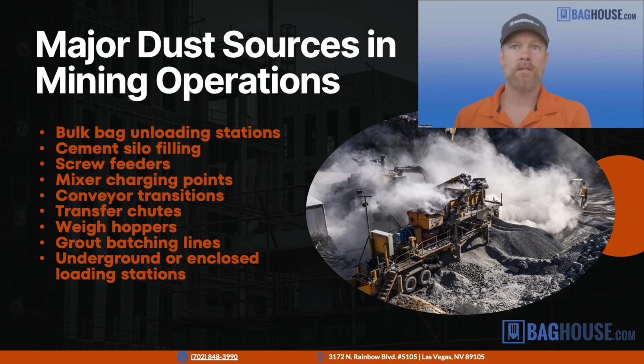If you're pulling dust collection air out of a facility, we also have to consider the balancing of the facility. So we don't want to have the doors slamming shut because we're pulling 60,000 CFM out of the facility and we're not recirculating it or making up that air. You can also be pulling dust in from outside. So usually we would look at recirculating air through the dust collector back into the building or have some sort of a makeup air unit to make sure that the ventilation balance in the building is neutral. So think about your facility. Do you have any of those issues? Are you noticing that when you go in, the door slams behind you? That's a balancing issue.